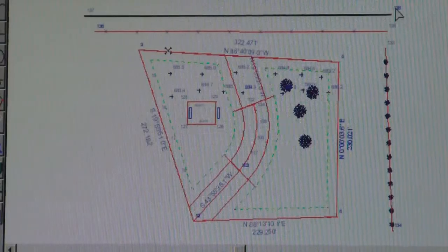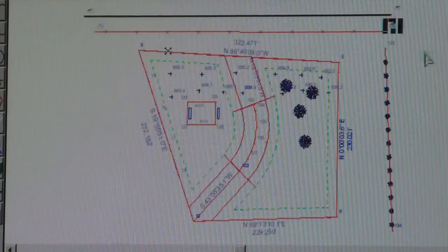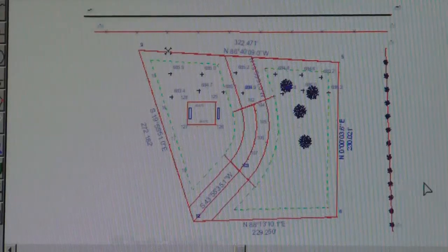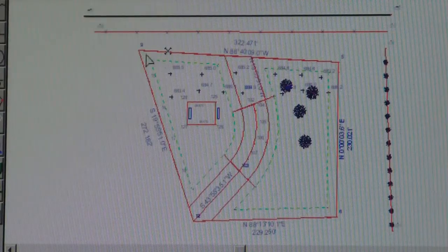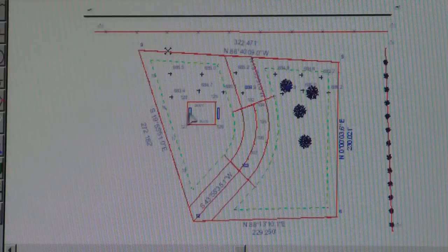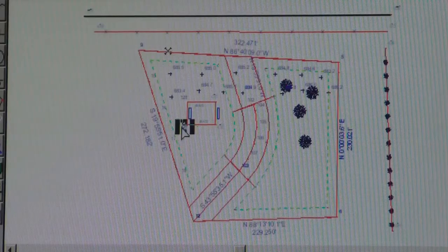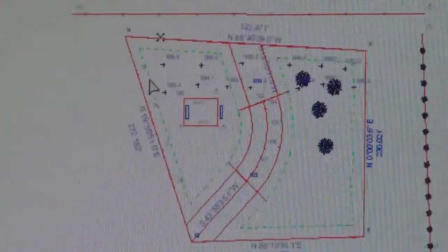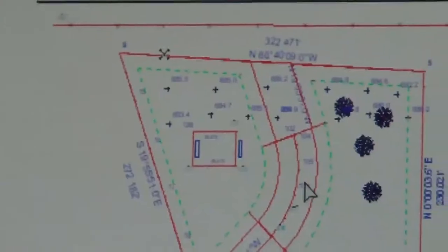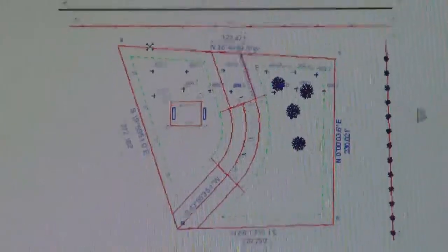Now once you have like edge of pavement, I would normally go in and delete the point numbers and the fence. I would get rid of that, the tree line numbers. We don't need those. The only thing you really need trees for, or point numbers for, is your traverse. And you will need one building corner, because I think you're supposed to locate that by 2 corners. I would dimension the building. The 4 points on a straight line, after you do that particular lab, you can erase those. You can actually get rid of all the points on the curve. Those are rarely shown on drawings.